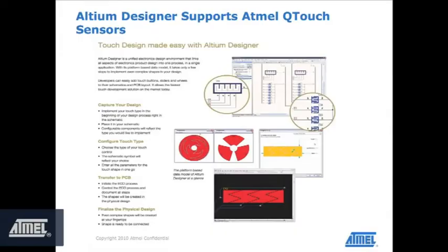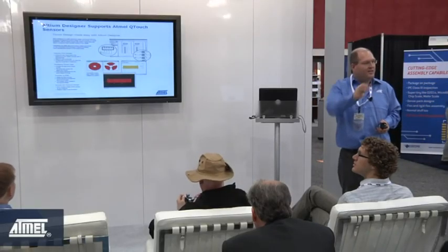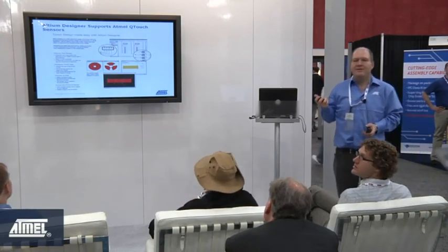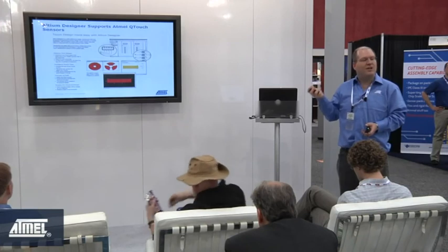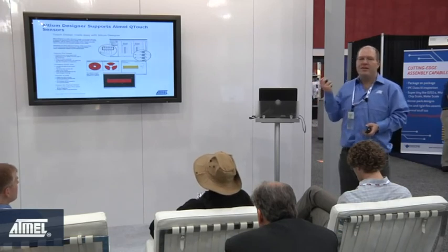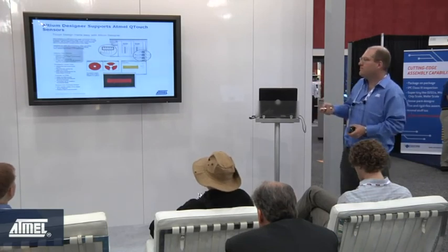What we've done with Altium, and this is valid for Altium Designer 9 and 10, is we have a built-in interactive studio plugin that plugs into Altium that allows you to pick, according to your design, specific button, slider, or wheel elements. And we have built-in pre-qualified PCB layouts, footprints for these devices. And you can work with pull-down menus to design the size and the resolution and the spacing of all the design rules around your hardware design, all automatically. So the level of success is much higher because you're now dealing with an interactive, more intelligent design system in Altium Designer that will help you design a really effective touch interface system. So we have now filled all 3 levels.